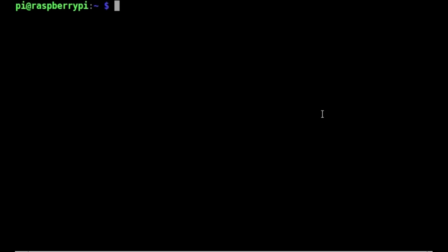When you plug your Raspberry Pi power in with the SD card, the HDMI cable and then your keyboard, you will be prompted for a username and password, and the default username is Pi and the password is Raspberry for all default images. You are encouraged to change it afterwards, but for this example I'm just going to leave it as standard anyway. So you'll end up with a screen like this, nothing magical to do.